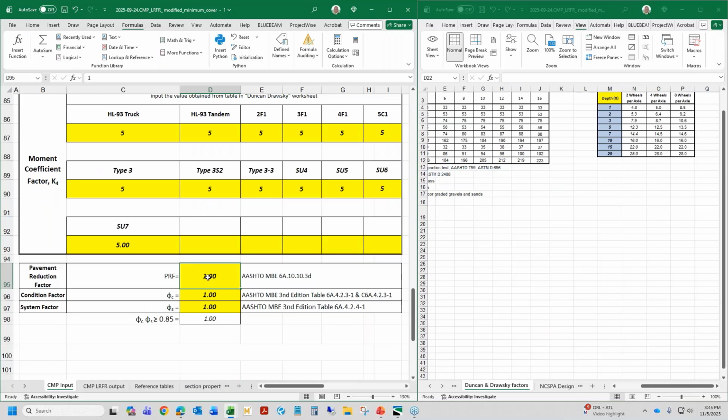The thing you have to realize about it and be careful about it is that when you do this, your load is spreading further, and so your patch is getting bigger. And what happens is now you have the potential for different axles to interact with each other where previously they didn't. So if you go through this process, you have to calculate what is the new load spread, and you have to figure out what is the new load distribution factor.